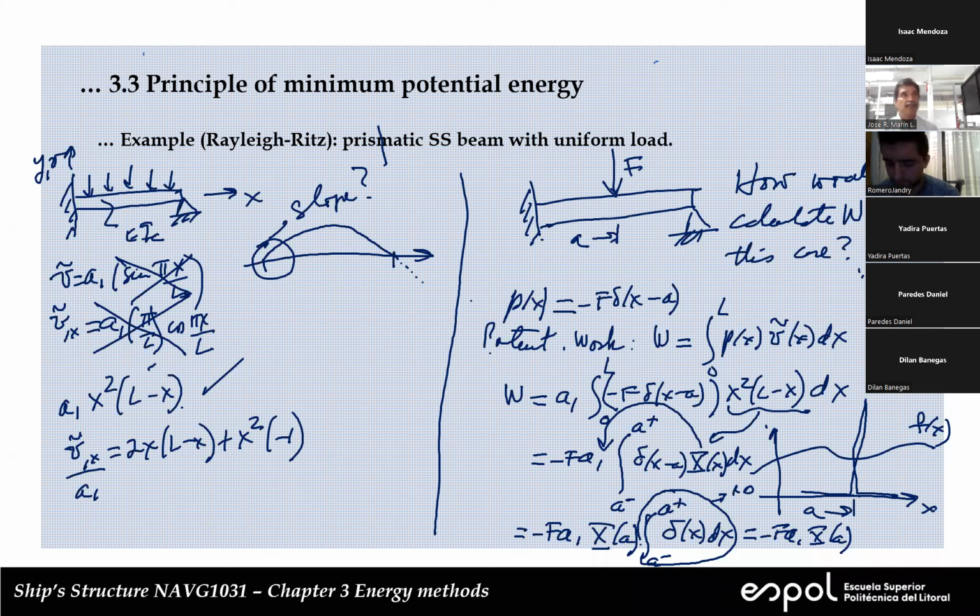So every time you have a concentrated force, it's very difficult to expect an exact solution, because the concentrated force gives you a spike in general. So that will give you a change in slope of the shear of the bending moment. So it's quite difficult to expect to have an adequate solution if you have a concentrated force. But still, we can apply it. Now, in the future, for example, when we go to finite elements, what we do is